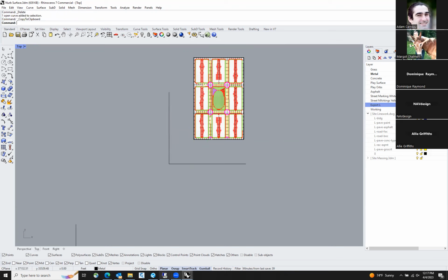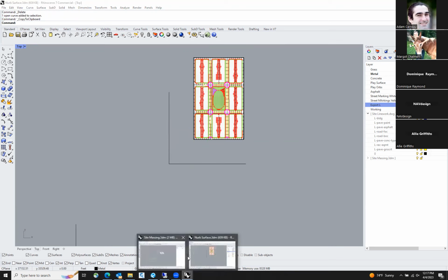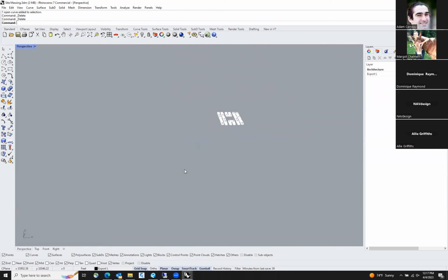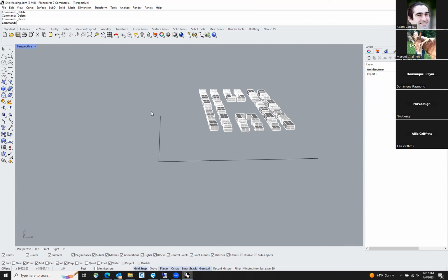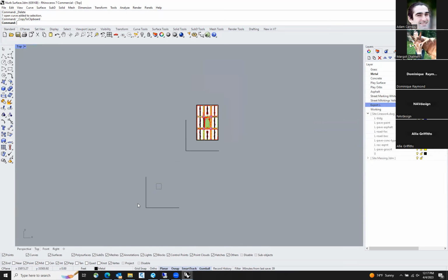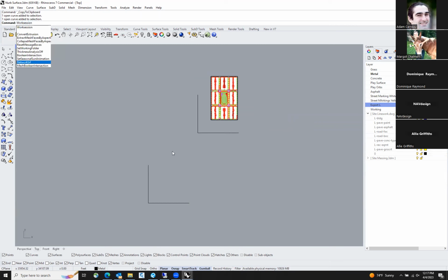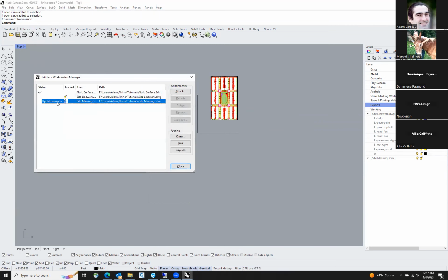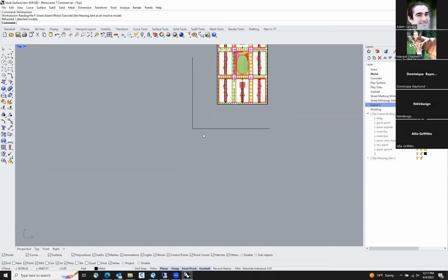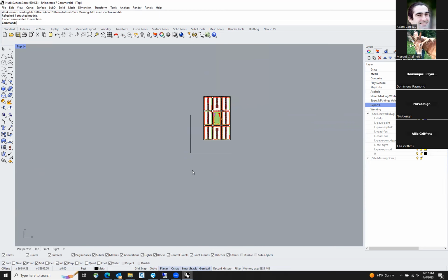I'm going to make sure that my architect's model has the same origin point, and you can go ahead and save that. And then as you can see, this is a work session. This is the architecture model, their previous export L. If you type in work session, you can see update available. You can just click update. And as you can see, it just updated with that new origin point.